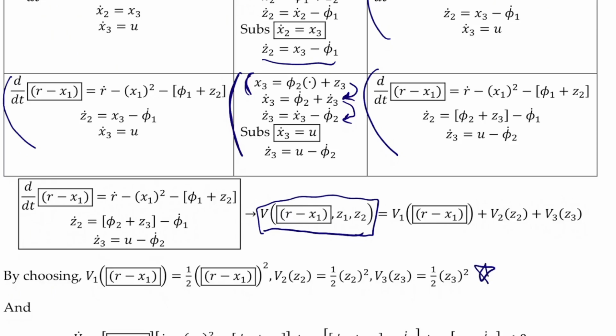This is the generic Lyapunov function, and we are going to take the time derivative of that, and of course V dot must be negative definite, right? And using V dot being negative definite, we will find a u such that this constraint is satisfied. Okay, the general idea of finding a control law using some type of reference or guideline Lyapunov function.